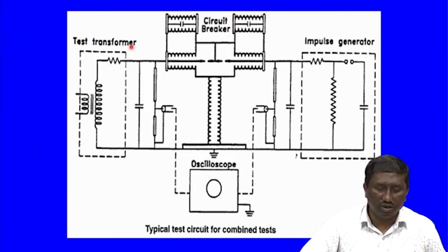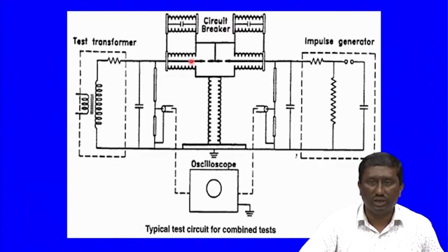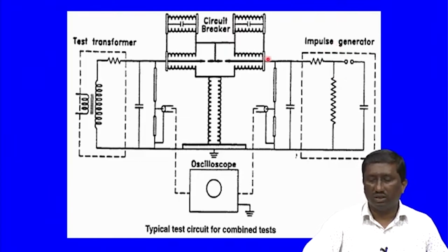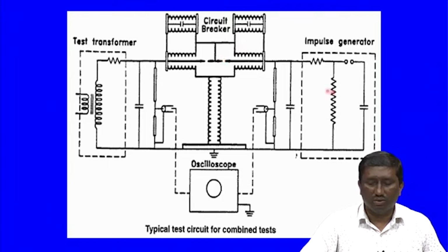The AC voltage is applied to the circuit breaker at its normal operating voltage or the voltage specified by the utility and the manufacturer of the rated equipment. At the instant the voltage is applied, superimposed on that voltage, a lightning impulse from the impulse generator is applied, so that the breaker performance is tested.